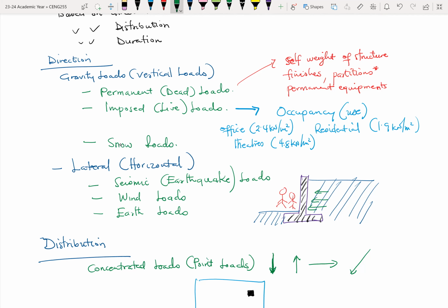So it is a load on the wall, and engineers design against these loads. Usually when the load is pushing against the wall, we call it an active pressure or active earth load. You do a lot of that in the soil related courses in second, third year maybe, where you go into active pressure and passive pressure to explain the different load mechanisms that the earth can have on a structure.